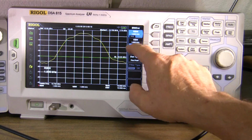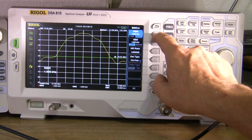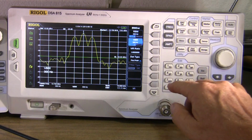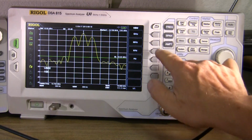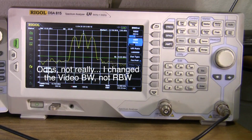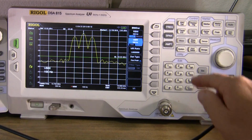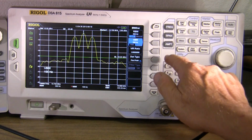The resolution bandwidth has been manually set. If I go to auto, it clears it up somewhat, puts it at 300 hertz, and so you can easily see the two sidebands there. I think I'd rather go to manual here and 100 hertz. It's going to slow the speed down, but it's going to give us a little better depth on the modulation there. So there's your 1 kilohertz video bandwidth.